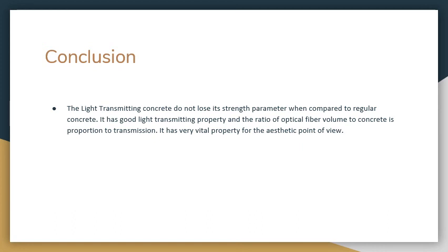The conclusion: the light transmitting concrete does not lose its strength parameter when compared to regular concrete. It has good light transmitting property, and the ratio of optical fiber volume to concrete is proportional to transmission. It has a very vital property from the aesthetic point of view.